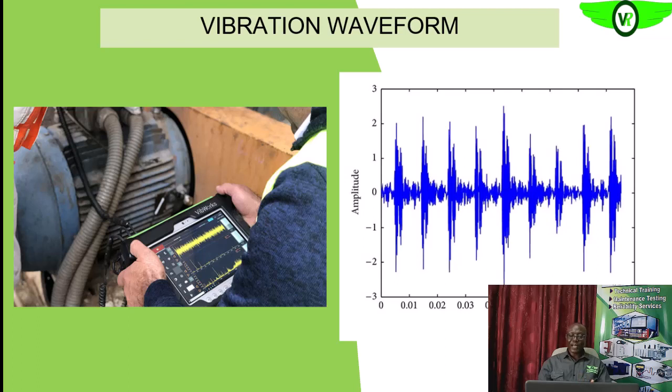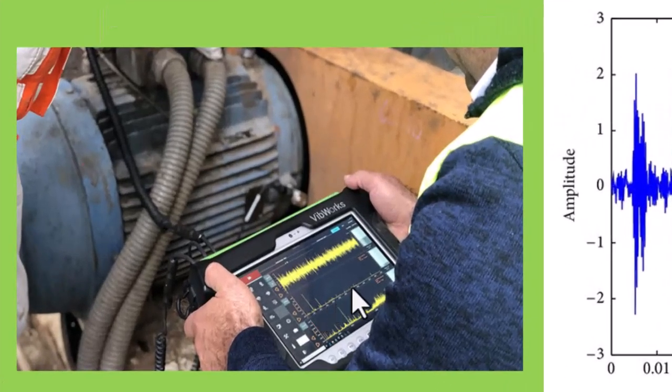When you carry out fast Fourier transformation on this, it will be able to separate the forcing functions that are superimposed into this kind of waveform that we are seeing into their respective frequencies. Okay, that is what we are seeing on this frequency spectrum. So you are seeing frequencies at different levels. So these ones are very high frequency events, which may be contributed by bearings.